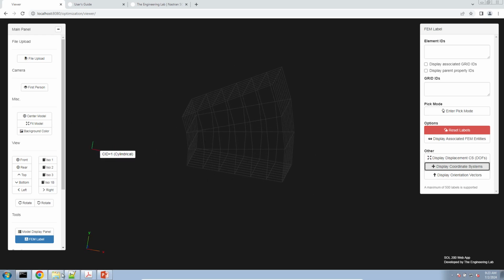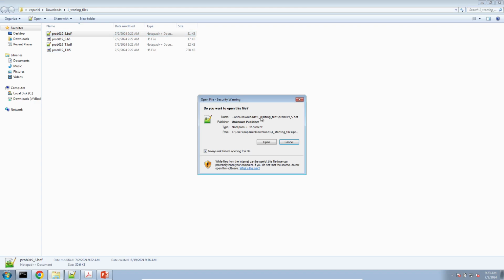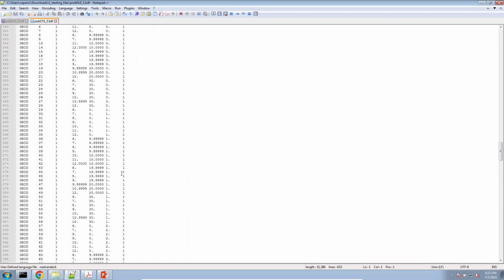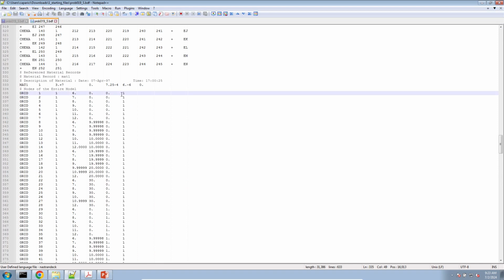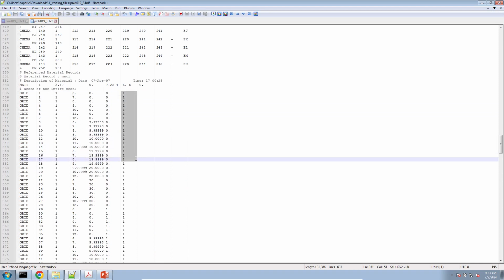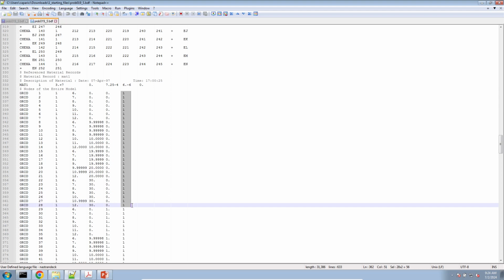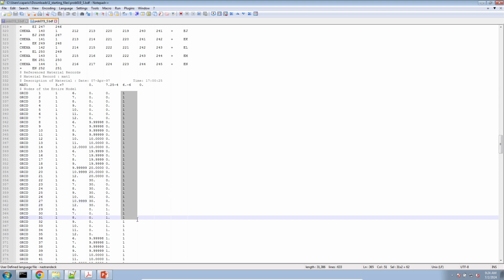If you look in the bulk data file and you look at the nodes, you'll see that the last column here, this is going to be field 1, 2, 3, 4, 5, 6, and 7. Field 7 is actually using a different coordinate system to define the displacement coordinate systems. It's in these displacement coordinate systems where the deflections are observed for each node.